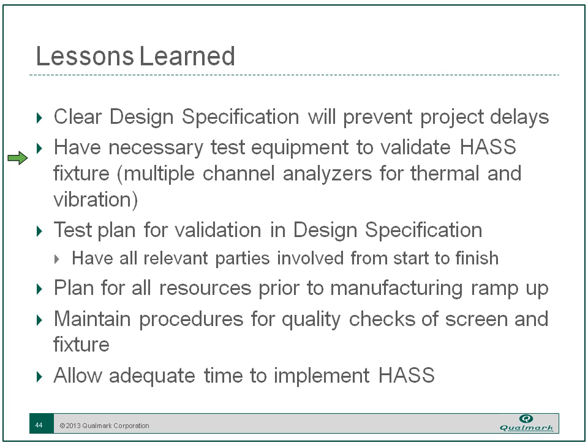HASS fixture validation is the most intensive use of my spectrum analyzer. And you often need a whole lot of channels of thermal data in order to verify what's going on in HASS. Have that test plan laid out, understood, and agreed upon with all the people that are going to be involved. Get the resources planned.